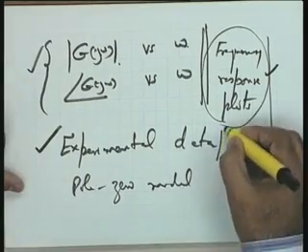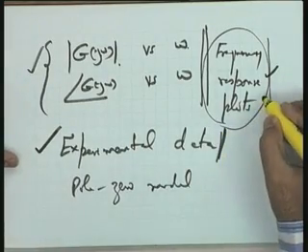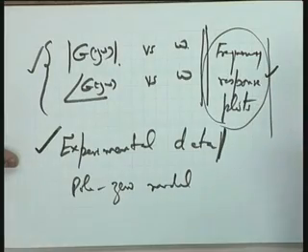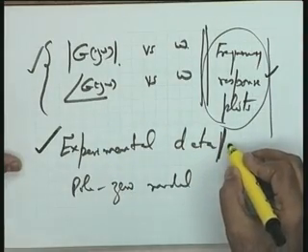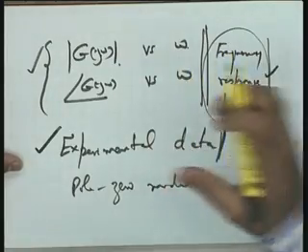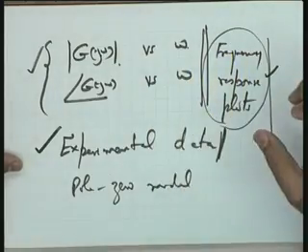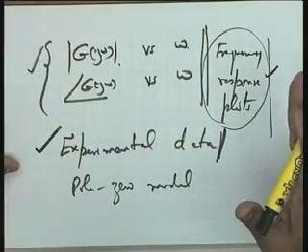Even through frequency response, for example, suppose you have got this experimental data, which is the frequency response data, and you want to use the root locus method. What will you do? This frequency response data will have to be suitably fitted into a pole-zero model, and that pole-zero model will be used for root locus design. But it should be very clear that this fit cannot be a one-to-one fit. You are definitely bound to make errors.